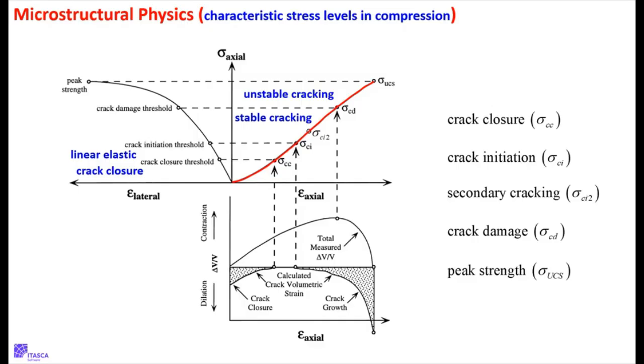Poisson ratio for rock is like 0.2, 0.3, which means you push it down 1 unit and it bulges out 0.2 units. And that means that when you work out the volume change, it actually is contracting. Okay. So if it was elastic all the time, this curve would just keep going up like this. It has this slope. Okay. So that's what we're measuring.